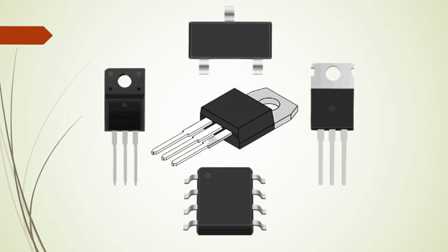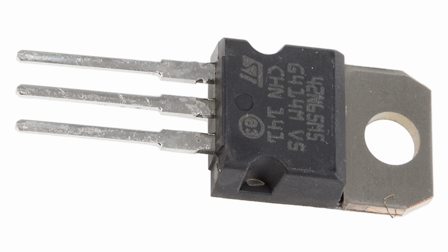1. High efficiency. Description: Power MOSFETs have low on-resistance, R_DS(on), which minimizes power losses during conduction. Advantage: This leads to higher overall efficiency in power conversion and management applications, reducing heat generation and the need for extensive cooling. 2. Fast switching speed. Description: Power MOSFETs can switch on and off rapidly, often in nanoseconds to microseconds. Advantage: Fast switching capabilities enable high-frequency operation, allowing for smaller components and reduced size in power supplies and motor controllers.